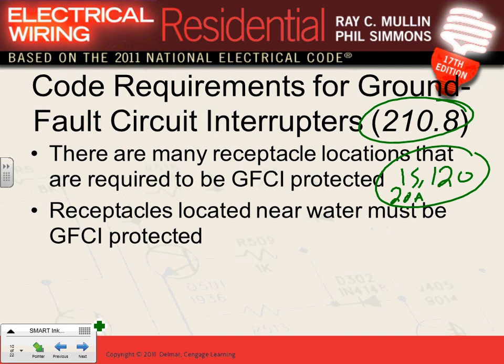What else? Did we forget anything else? So these are any place where there's water or dampness, need a GFCI. In a dwelling, that will make you within 6 feet of any sink, kitchen countertop, bathroom, unfinished basement, outdoor, and garage. Everybody got that one? In a non-dwelling, for the most part, the same thing. Within 6 feet of a sink and everything outdoor have to be GFCI. So that's where your GFCI location is.